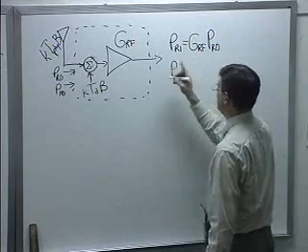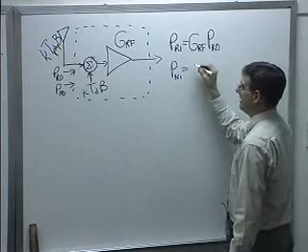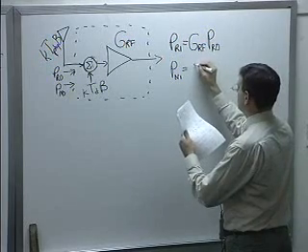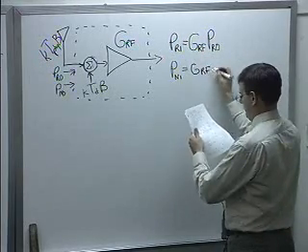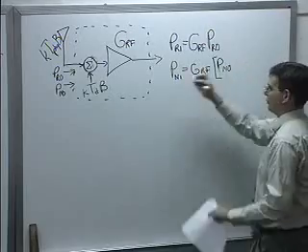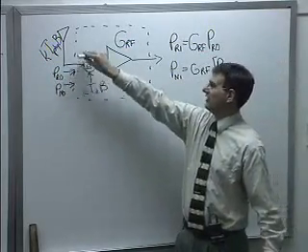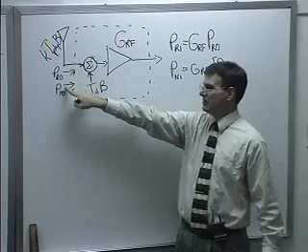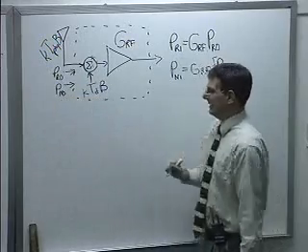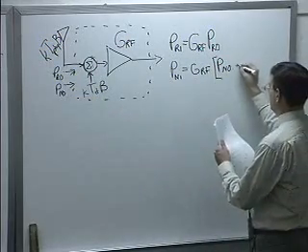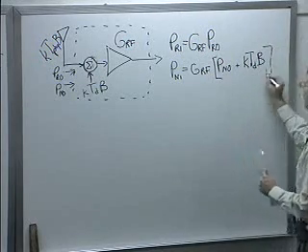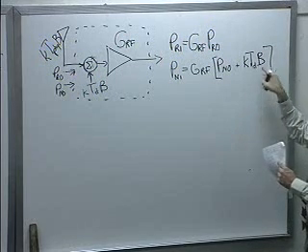And what comes out as noise on this terminal is basically my G RF times my original physical noise power. Of course, it goes through gain. If this is in-band noise power, you can't add gain to your received desired signal and not add it to your noise power, plus k T sub d B. Boltzmann's constant, device noise temperature, and the bandwidth.